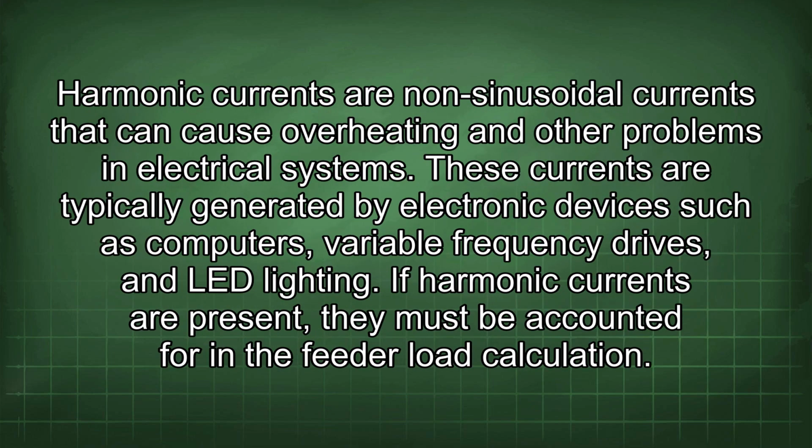Harmonic currents are non-sinusoidal currents that can cause overheating and other problems in electrical systems. These currents are typically generated by electronic devices such as computers, variable frequency drives, and LED lighting. If harmonic currents are present, they must be accounted for in the feeder load calculation.